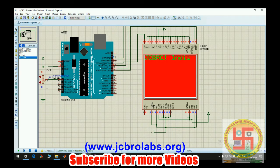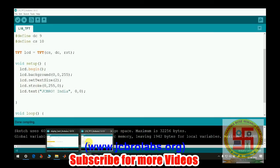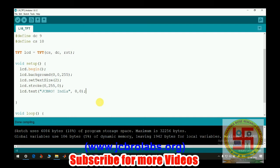Let's write something else in the next line. LCD.text "think India". Its X location should be 0, and as we discussed, size is 2, so 14 pixels are used for the Y location.